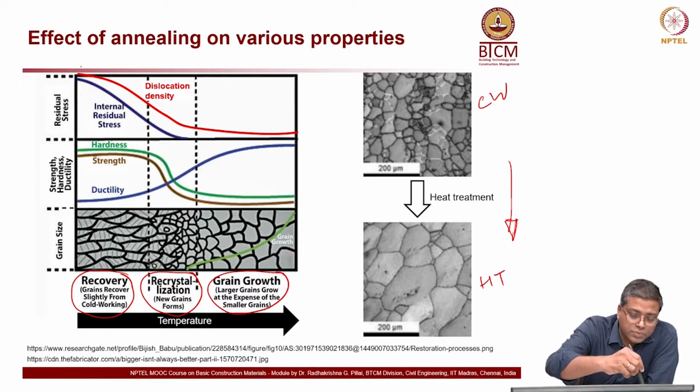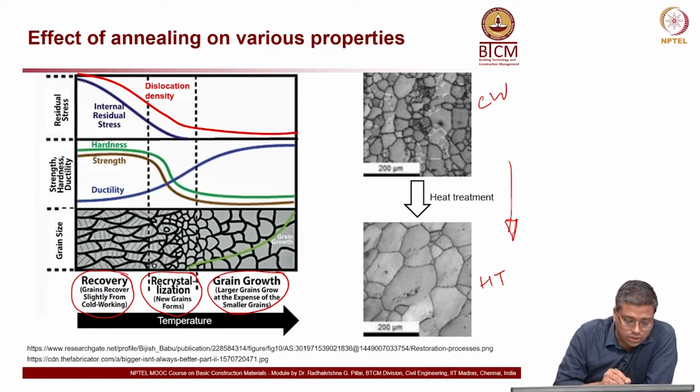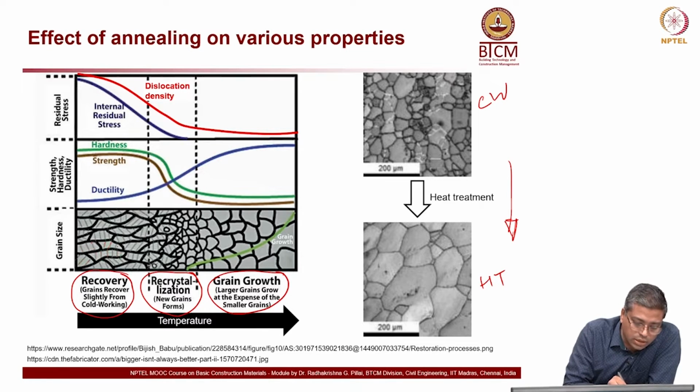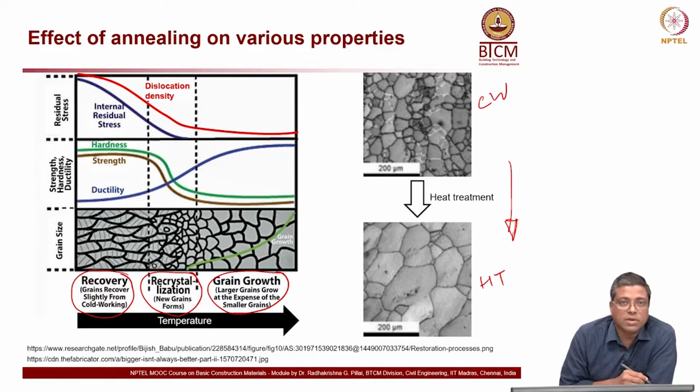So here you can see, look at the dislocation density, first thing to look at. You can see here there are all these light gray lines, they are the dislocations present in the material. Okay. Now, you have these dark lines here, which indicate the grain boundaries. So you can see several grains over there.